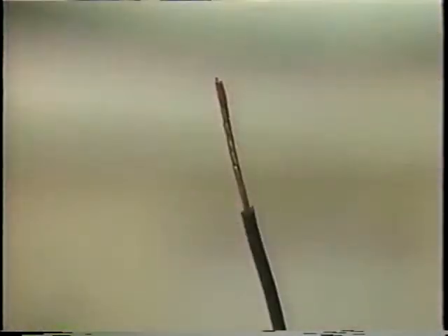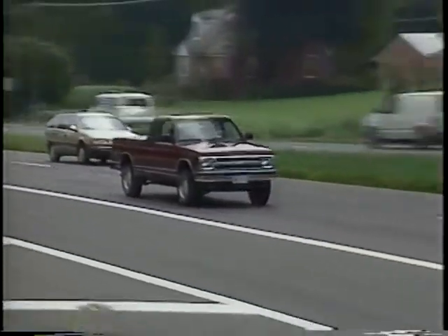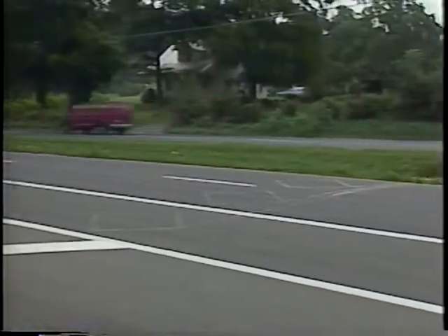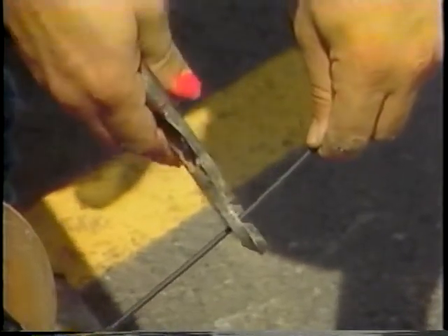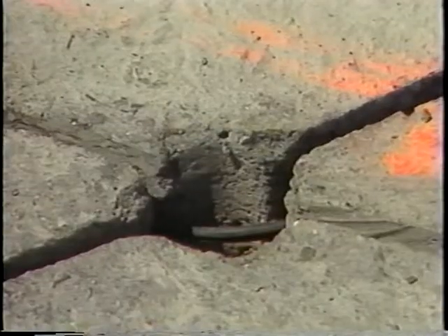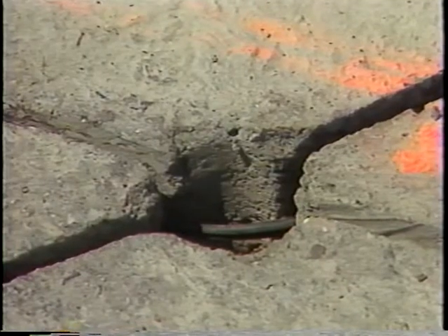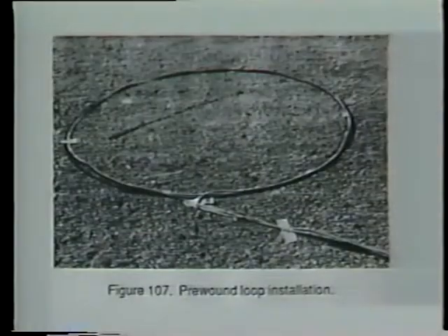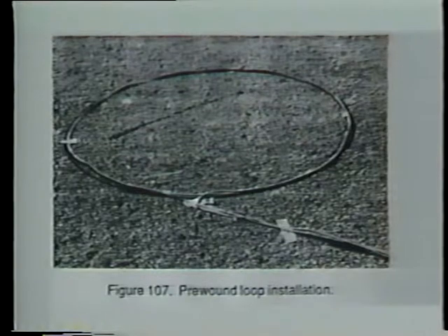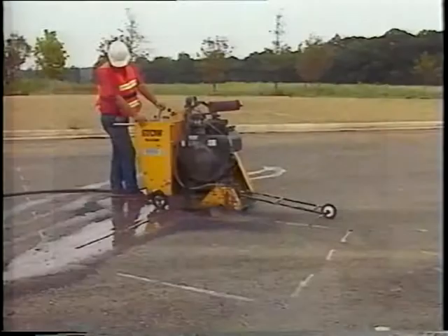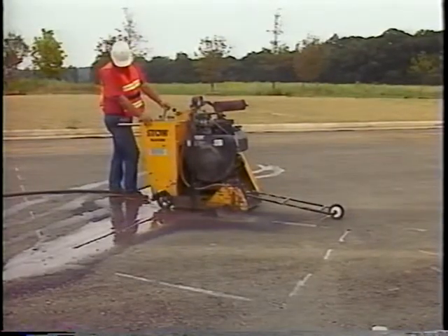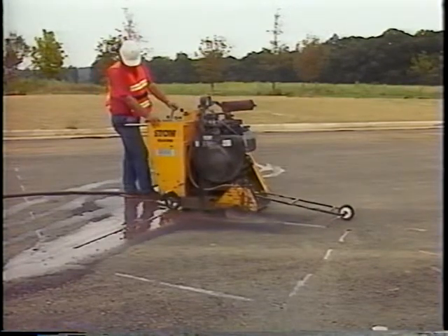The wire insulation must withstand wear and abrasion from shifting streets, moisture, solvents, and oils, as well as the heat of high-temperature sealants. Wire encased in continuous cross-linked polyethylene tubing is popular due to its durability, flexibility, and heat resistance. Some agencies pre-wind and bind loop wire to the exact specifications in their shops, making a prefabricated loop to transport to the site. Best suited for smaller loops, this procedure significantly reduces on-site installation time.